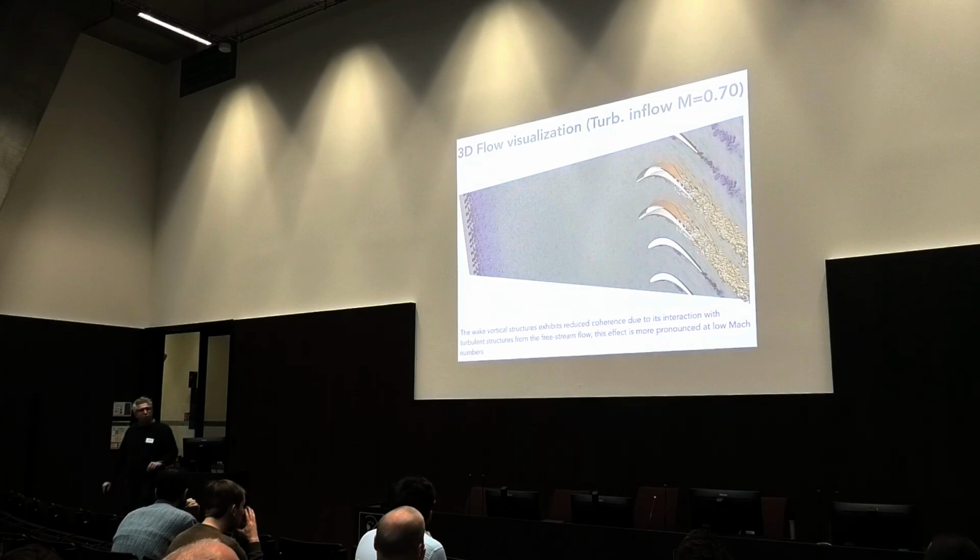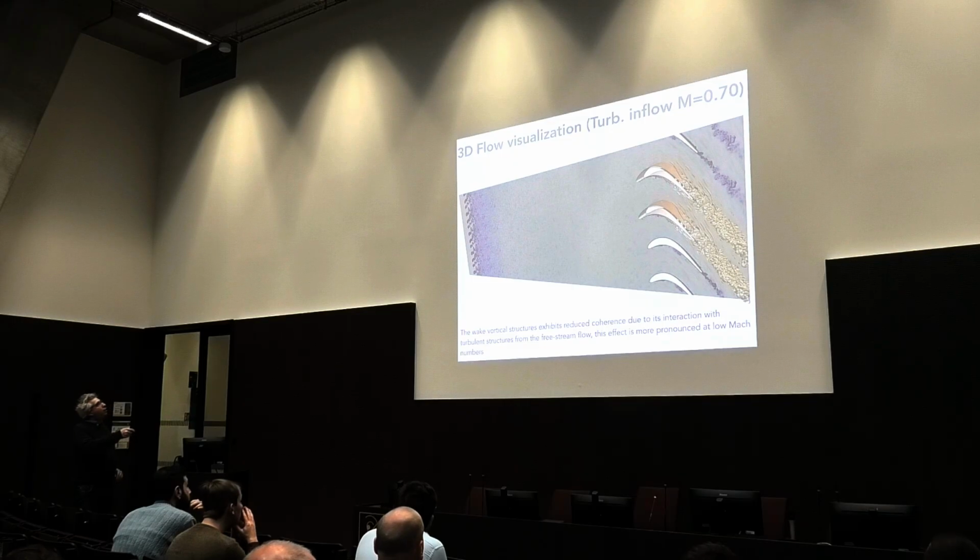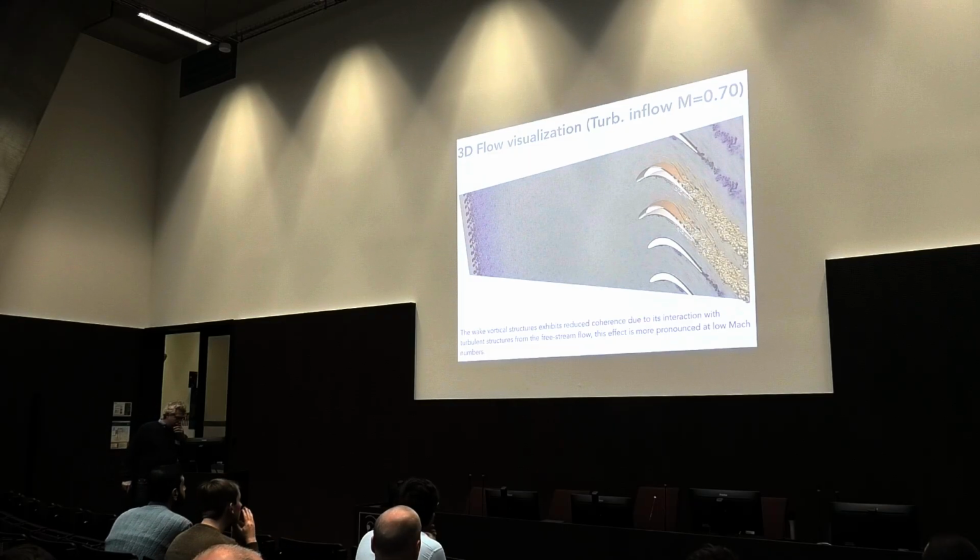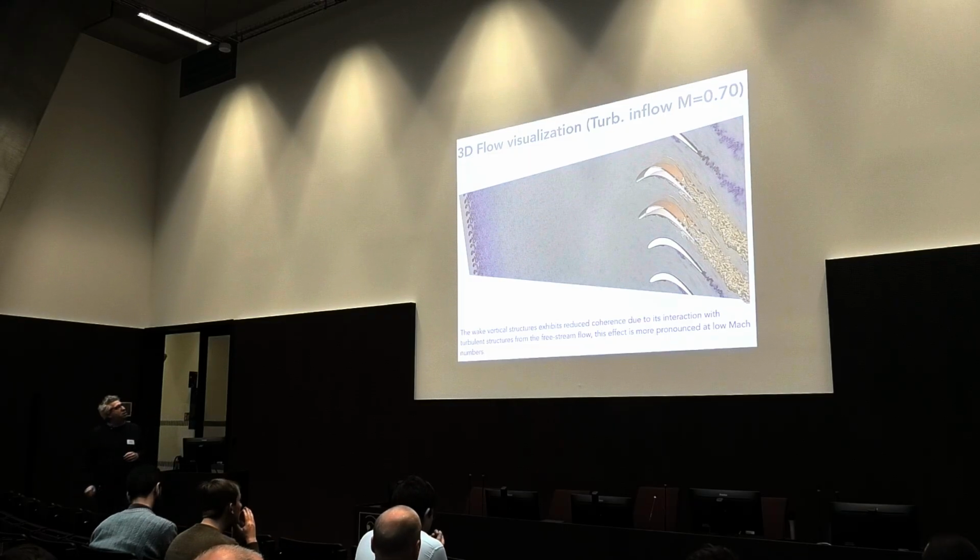Now, if we put the turbulence grid, so let's recall that here we emulate this row of cylindrical bars, but we don't mesh them, we just replace them by a source term, a force source term in the Navier-Stokes equation. And in fact, it is a convenient method to inject turbulence.